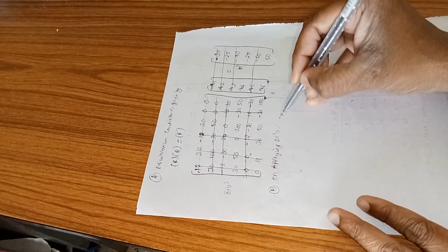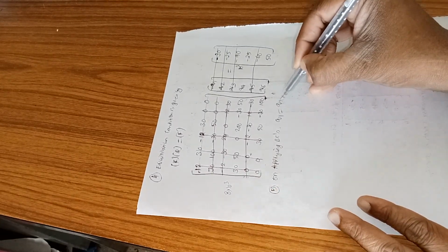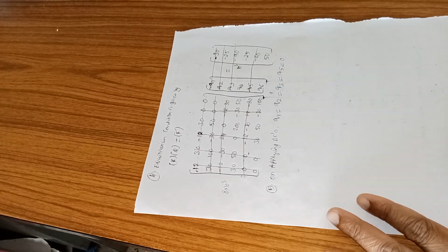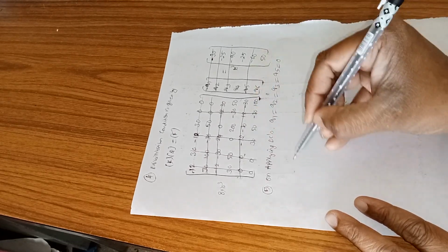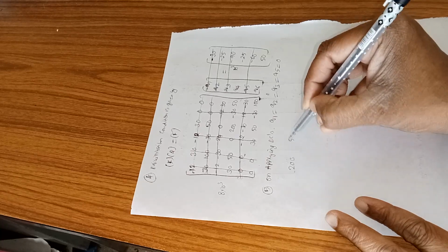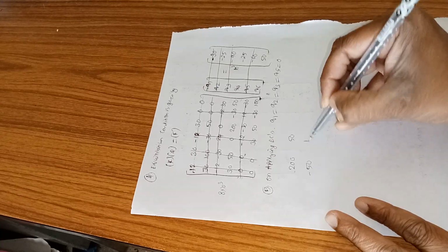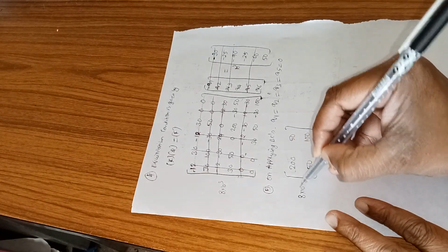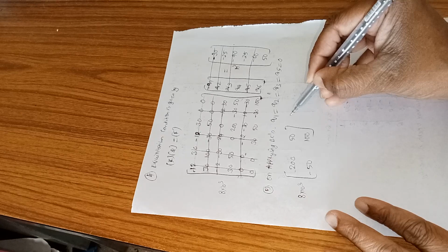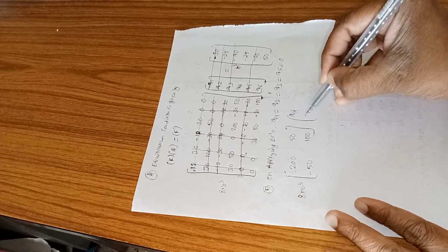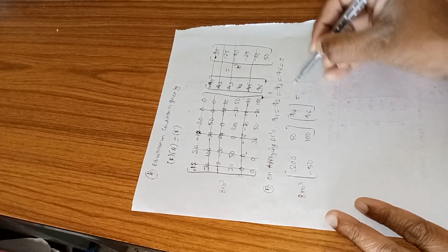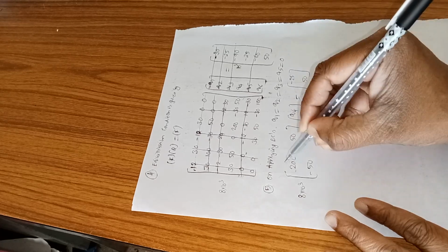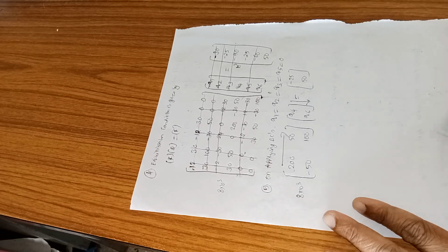As I eliminate that, I'm going to get q1 equal to q2, equal to q3, equal to q5, that is equal to 0. Once I have eliminated all of them, I'm going to get 200, 50, minus 50 and 100 from the fourth and sixth columns. And here this 8 into 10 to the power of 3 will remain common. And here I'm going to get q4 and q6. So q4 and q6. And here I'm going to get minus 25 and 50. Now let me do the matrix multiplication for both these.